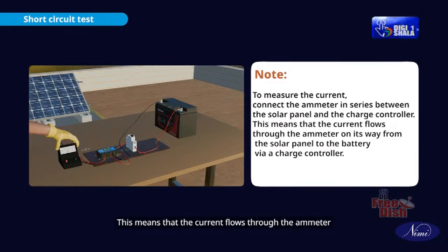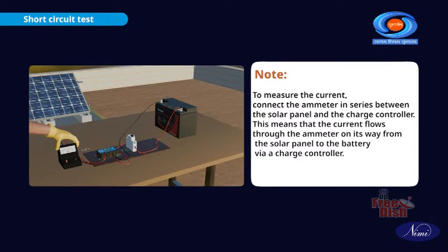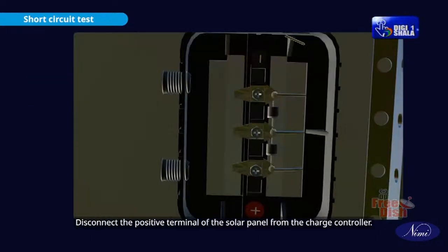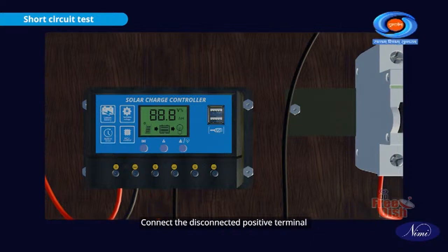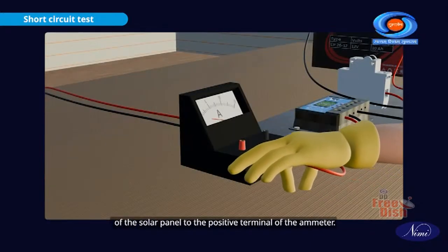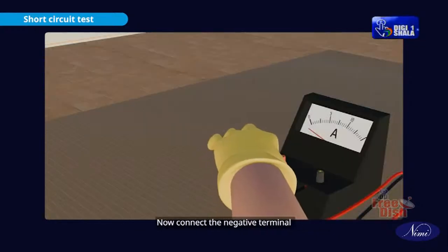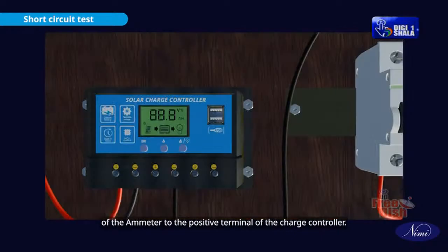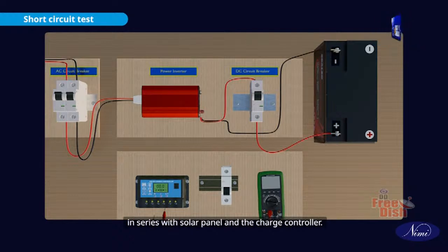This means that the current flows through the ammeter on its way from the solar panel to the battery via the charge controller. Disconnect the positive terminal of the solar panel from the charge controller. Connect the disconnected positive terminal of the solar panel to the positive terminal of the ammeter. Now connect the negative terminal of the ammeter to the positive terminal of the charge controller. This connection puts the ammeter in series with the solar panel and the charge controller.